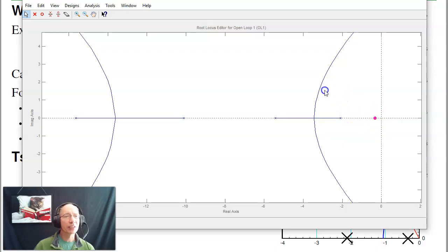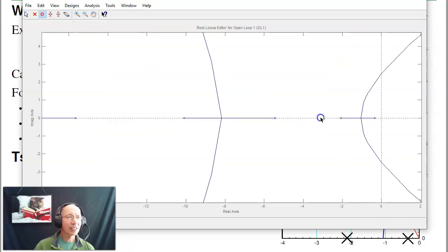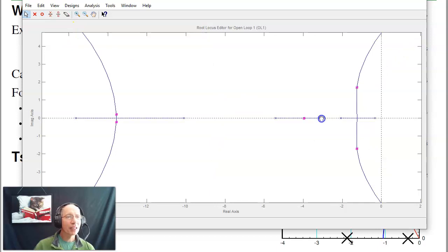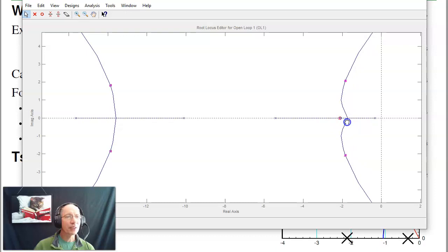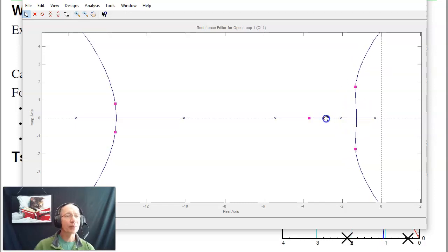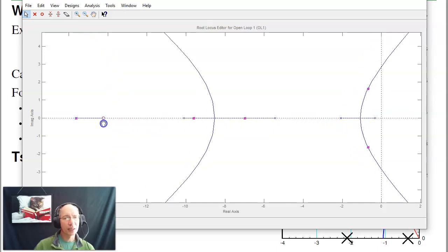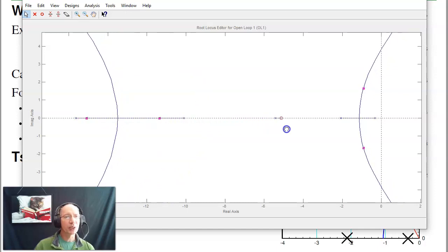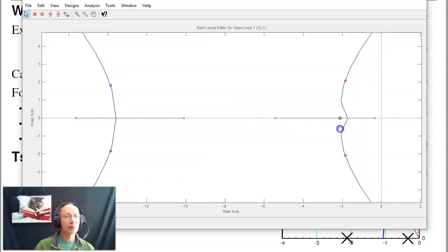In contrast, let's erase that zero, add it back. In contrast, if I got rid of this pole, not the slowest pole, but the next slowest pole, and here I didn't get exactly right, I have pulled the root locus left. Again, comparing it, you'll look at this part of the root locus. If the zero is way over here, the dominant part's right around -1. As I bring the zero left, I'm pulling the root locus left. And that did speed up the system.